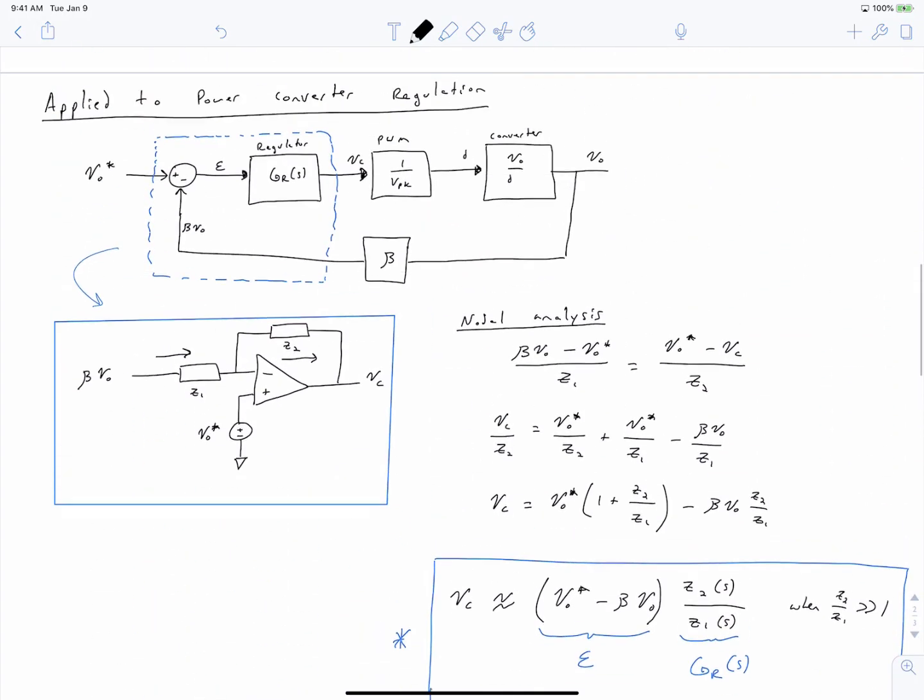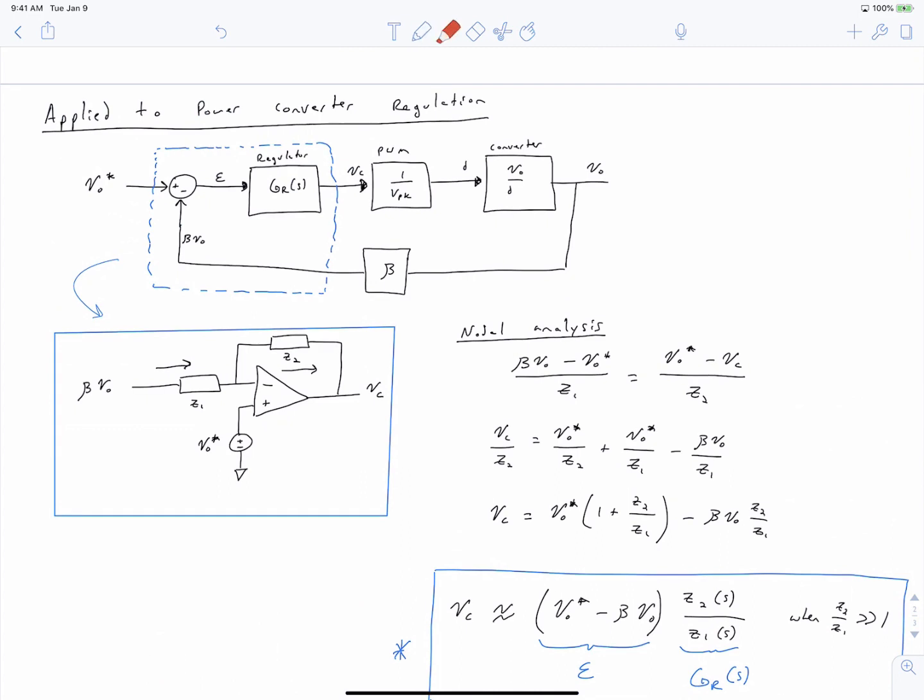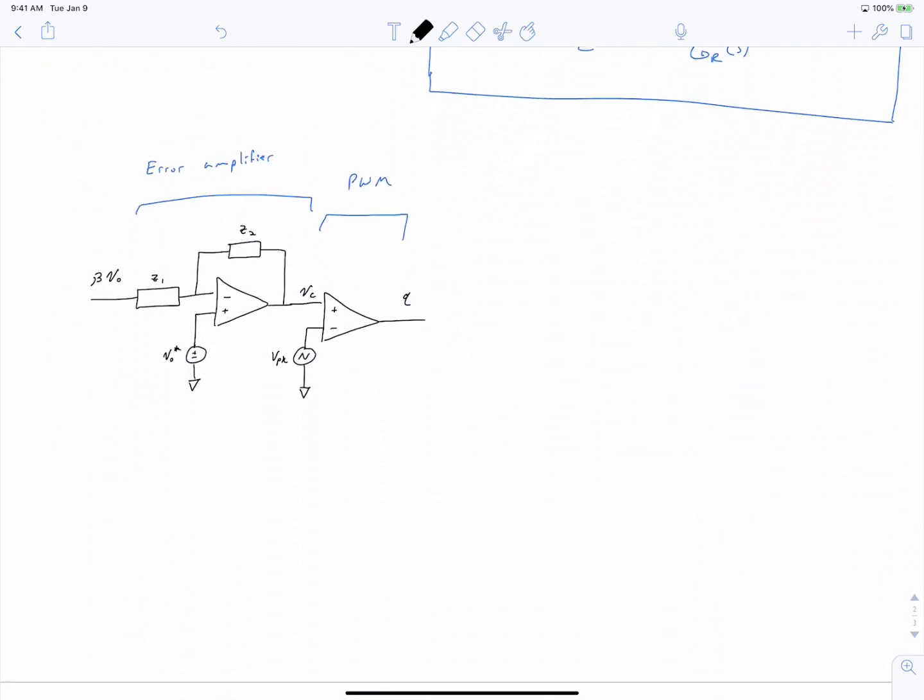So above we've been indicating that the output of our PWM stage is a duty ratio, and that is the block diagram version of what our circuit is. However, in all actuality, the output of our PWM interface is an on-off binary gate signal that goes to the gate of our MOSFET. And in this case, we'll send it through a gate driver. The gate driver isolates the gate signal so it can be connected to the gate of a MOSFET, and it also amplifies the signal to have the correct voltage levels that are needed to turn on and off our MOSFET.